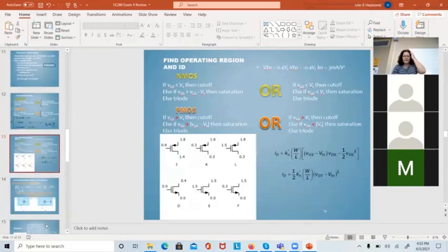And then the other trick here is you get pictures like this, and you don't know which symbol is which. Can you tell me if it's PMOS or NMOS? The ones with the arrows going into the transistor are all PMOS. You tell which symbol it is. This is the first part of the problem. Can you tell which ones are NMOS? The NMOS have the arrows going out. Arrow indicates current direction of flow. So current's flowing here, that way, it's current's flowing downhill.